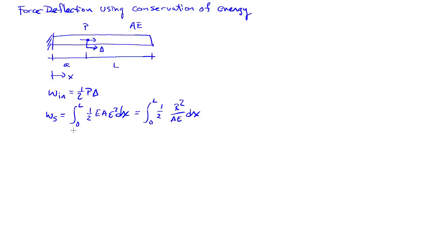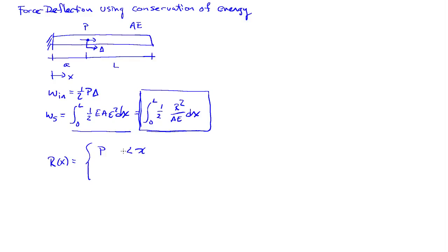And the version that you use, either the kinematic expression or the force expression, really depends on the problem at hand. So whatever is convenient to determine for the integrand, we're going to use. So in this case, we're going to go ahead and use the force formulation because it's easy to know what r of x is. And so for this problem, simply from statics, r of x is equal to P for x between 0 and a, and it's 0 for x between a and L.